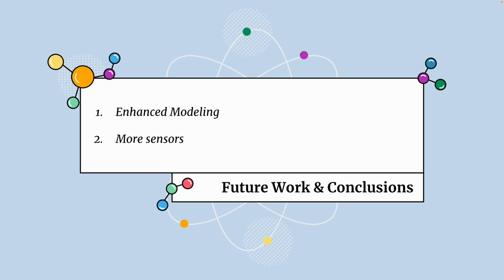So in conclusion, this system is built on the Raspberry Pi and monitors the temperature in the environment using the DHT sensor. It not only reads the current temperature and humidity, but also predicts the future temperature trend using a simple linear regression model. When the predicted temperature exceeds the threshold, the system will activate the fan. The current sensor data, the prediction, and all the information can be displayed on the LCD screen.